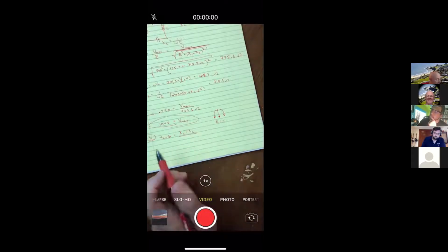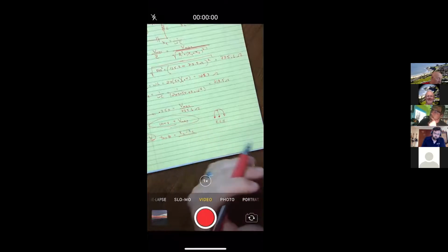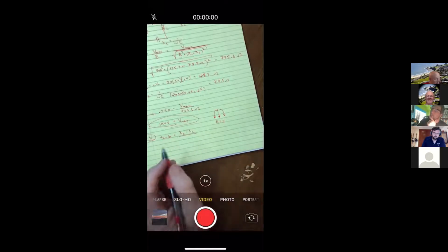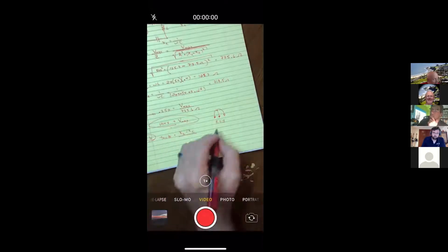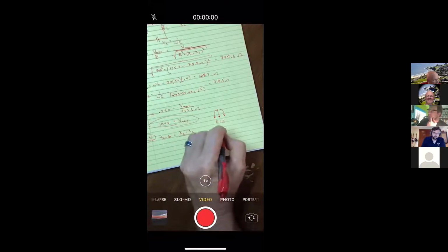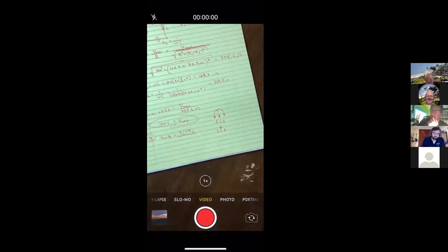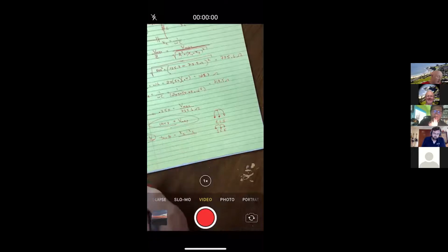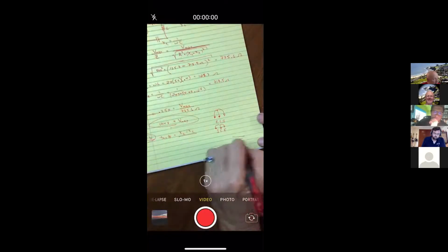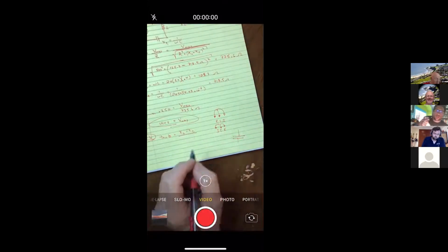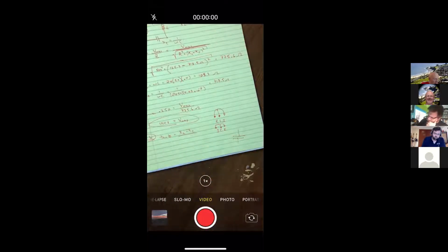And so anything that behaves more like an inductor would have the voltage come before the current. Another nice phrase is ICE, because again, we can use the C for the symbol of the capacitor, and then the I comes before the E. And this one's hopefully pretty obvious too. You have a capacitor, you're not going to get any voltage on it till you actually put charge on it. So you have to have the current flowing before you have anything in it.